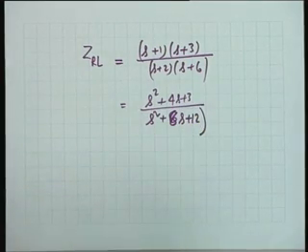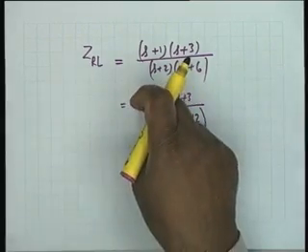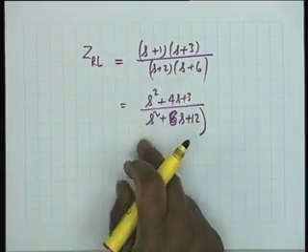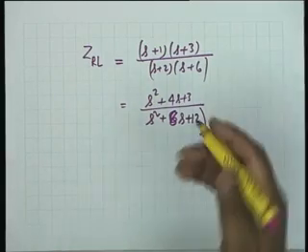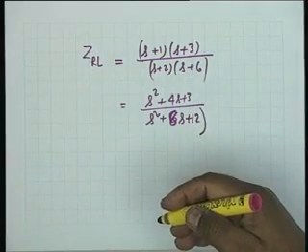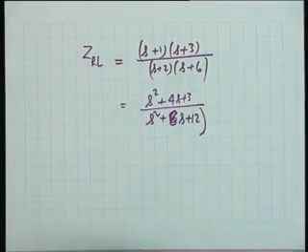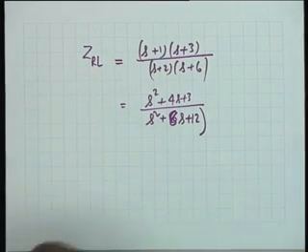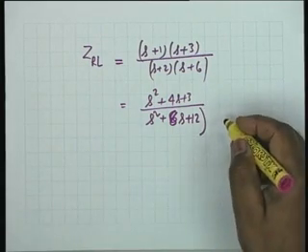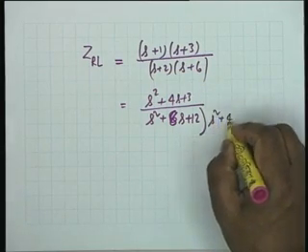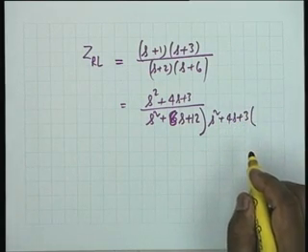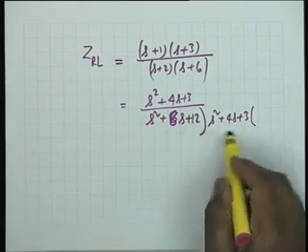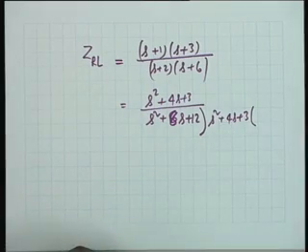No, because if I do that, I shall be removing the infinite frequency value of ZRL, which is not permitted. Therefore, I must take the reciprocal and then start continued fraction. This is the point that if you do it blindly, you will come back. Let's say, don't do it again, because you will get negative value. You see, you will get 8s here, so minus 4s and so on. Then you know you have made a mistake. You have to come back.